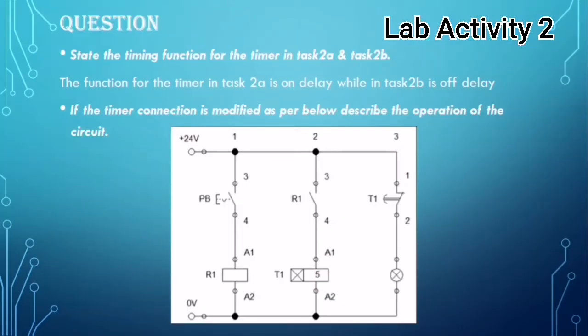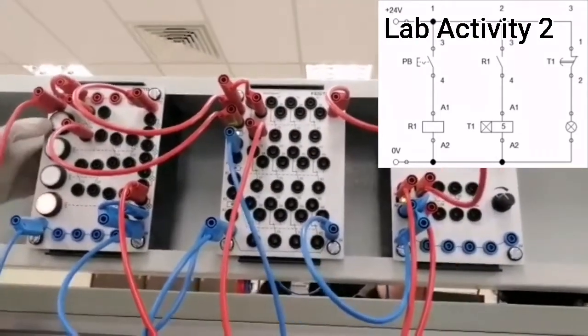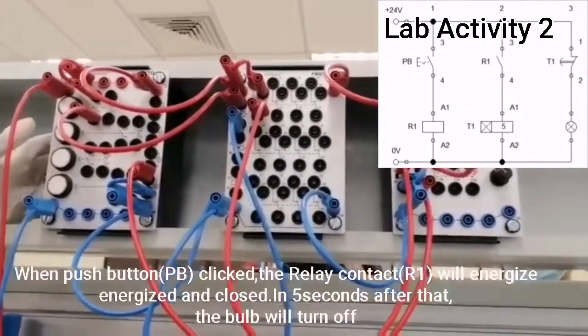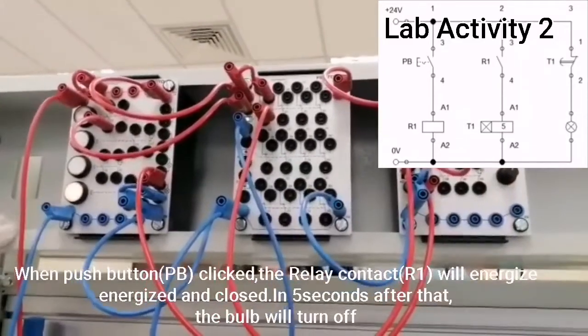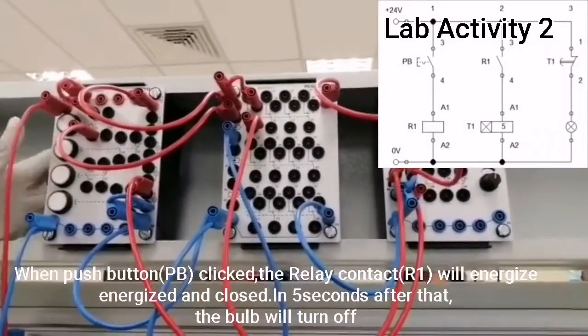Okay, now for lab activity 2 questions. First question is state the timing function for the timer in task 2A and task 2B. The function for the timer in task 2A is on delay, while in task 2B is off delay. The next question is, if the timer connection is modified as per below, describe the operation of the circuit. Okay, as we refer to the experiment and the circuit, when the power supply is connected, the bulb turns on. And when push button PB is clicked, the relay contact R1 will energize and close. 5 seconds after that, the bulb will turn off.